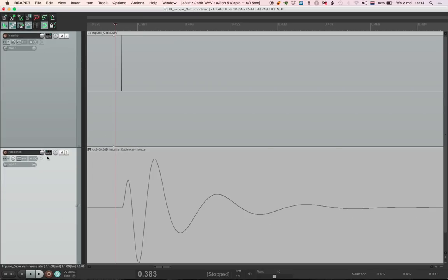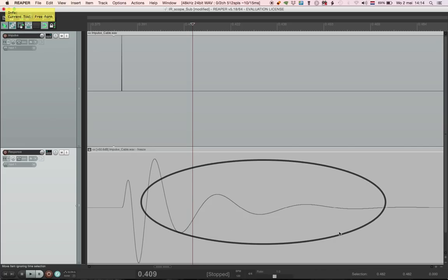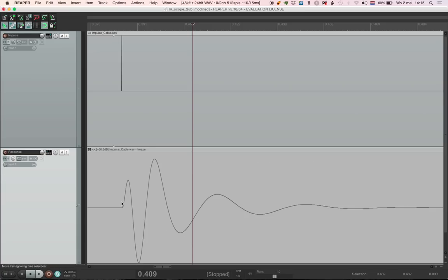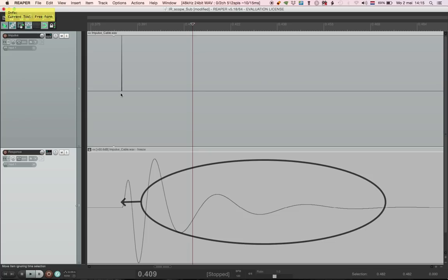However, if we look at the response to that impulse of our device under test in track 2, if I scrub over here, you would not expect to hear any sound because there's no data, there's no amplitude. However, unlike our input, in the output, when I scrub in this portion, there is very much signal, there is very much data, there is amplitude. And clearly, not all frequencies are being delivered simultaneously, because everything we see over here is of course later than the initial impulse response that we started out with.